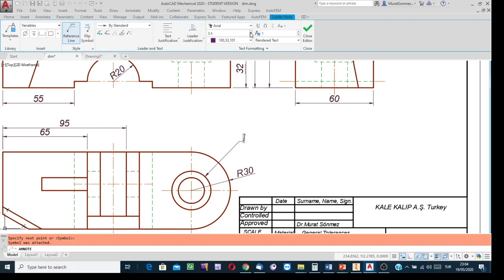Font height: we already configured the text facility, but here, as the number, do not select a font height. Multiply the recommended font height by the inverse of the scale factor. The scale factor in this example is 1 to 1. The inverse of 1 to 1 is 1. So 1 times 5 is 5. So select 5. And then the rest.